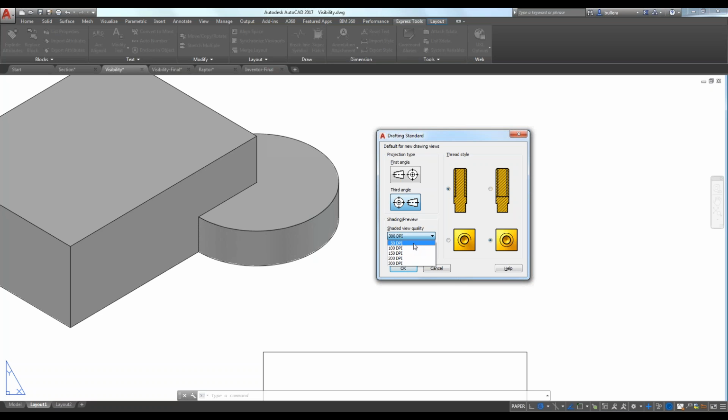If you're doing draft reports and you don't want to use up a huge amount of ink, or you really don't need that high resolution, we could keep that DPI low, and then once we're at a point where we're creating these views with the intention of going to a final report or out to our clients, we can up that to 300 DPI. So this is essentially where we would do it. And again, it's important to have this set and identified before you create the view base.